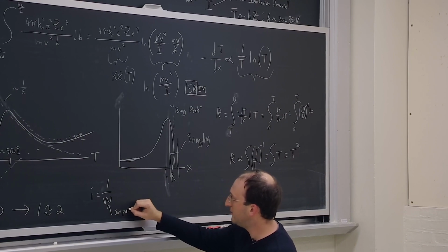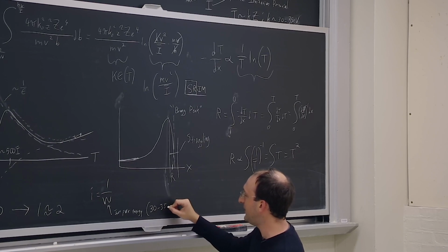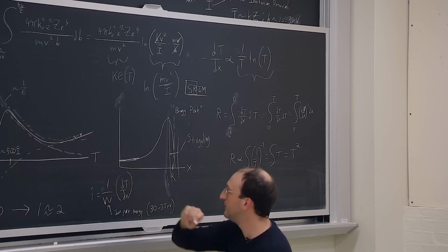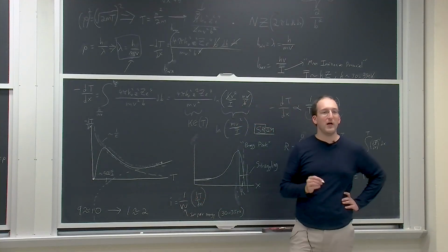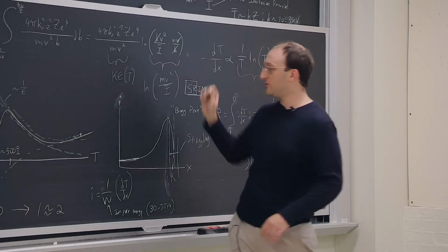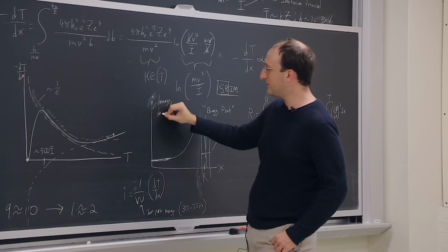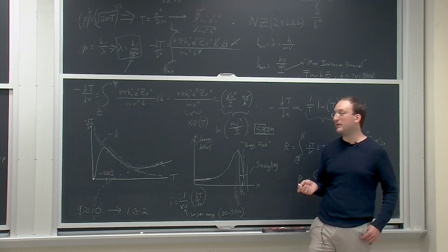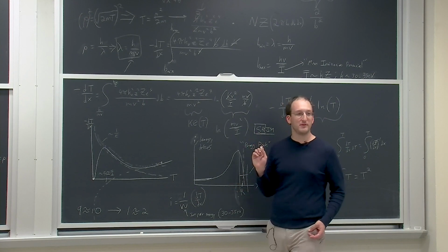ion pair energy, usually around 30 to 35 eV, depending on the material, times dT/dx, which is to say when the stopping power is higher, you're going to have more ion pairs produced as a function of distance. So the real label for this y-axis here should be like ion pairs, or damage, or defects, or anything like that that refers to the same kind of thing as damage to the material, either by ionization or even by similar nuclear processes.